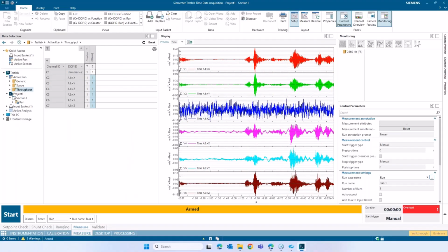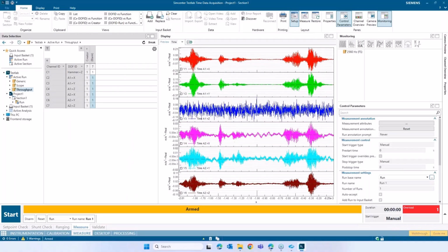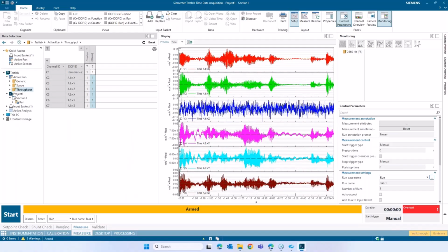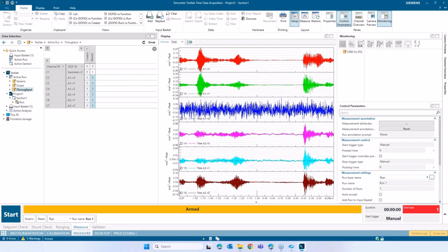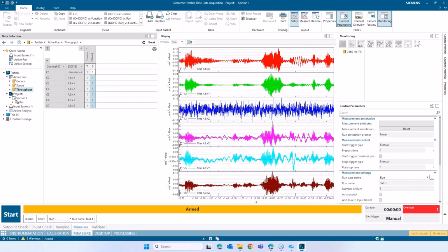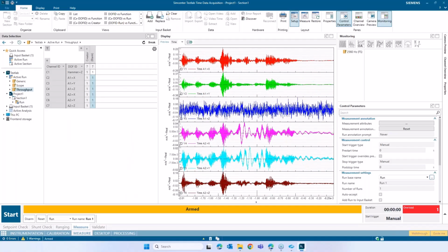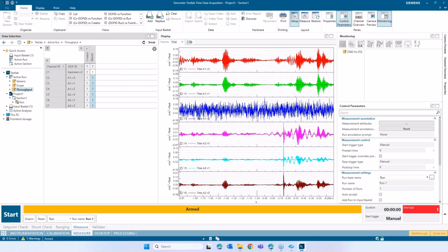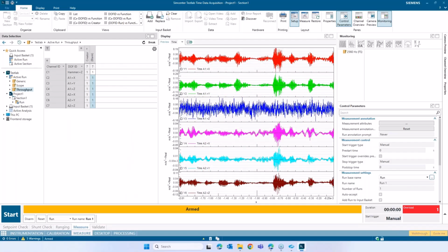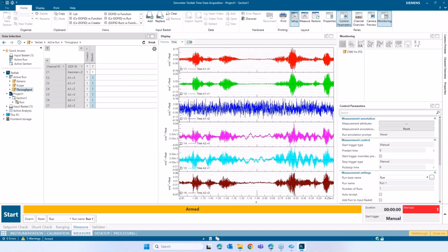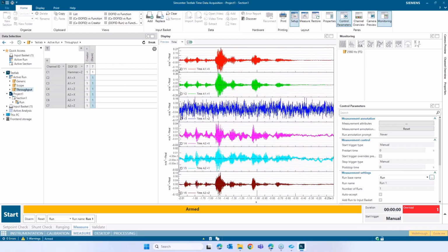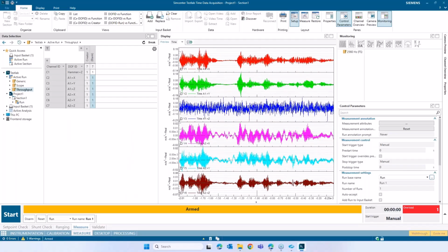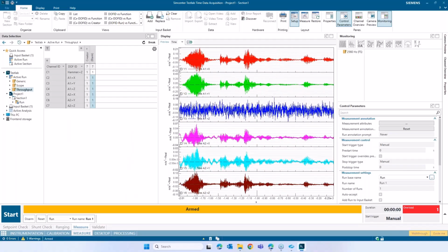So let's see how that works when we are actually live taking the data. For this case, I'm going to use Simcenter Testlab Neo's time data acquisition module. This is the general purpose data acquisition module, equivalent to the signature acquisition in Testlab. Like you want to collect some operational data. You have mounted some accelerometers and microphones, you're running the test at different operating conditions, like vehicle speed or engine speed, and then you're taking the data. So this time data acquisition is meant for that.